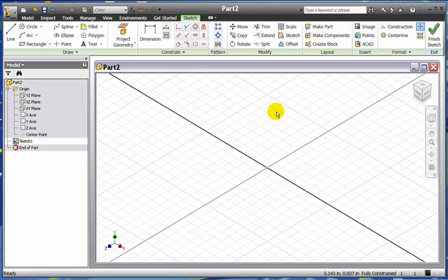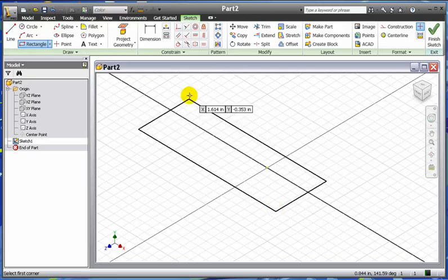Now the dimensions of this, just the basic rectangle, so we're going to start by doing the bottom rectangle. It's 2.5 inches long and it is 1.5 inches deep. So I'm going to grab my rectangle and draw my rectangle, and I drew it in this direction because that's the direction that the part goes. Do not draw it in this direction.